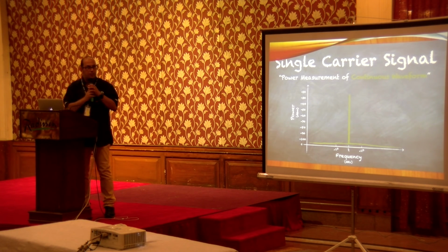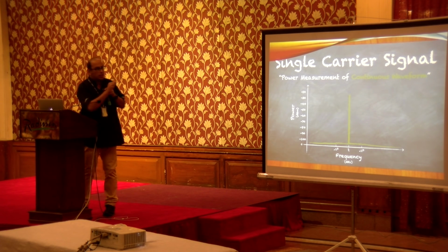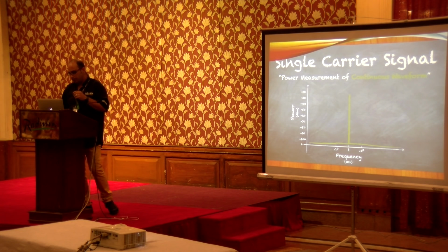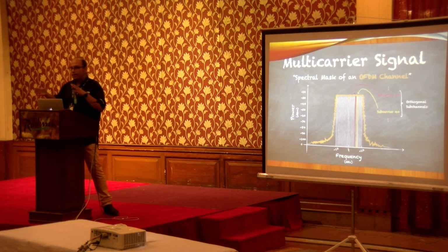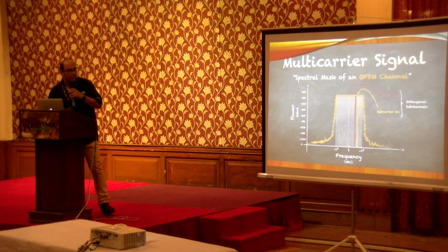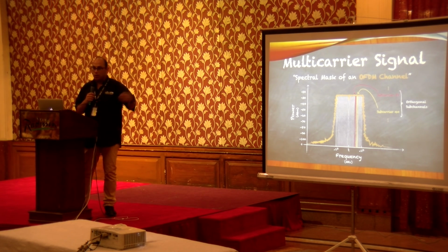So 5550 is the carrier signal. We call it the carrier signal. But actually, each of these spectrums can carry your signal. So when you are using a wide channel width, like 20, 40 or 80 megahertz, you can have more throughput because you are using more spectrum.